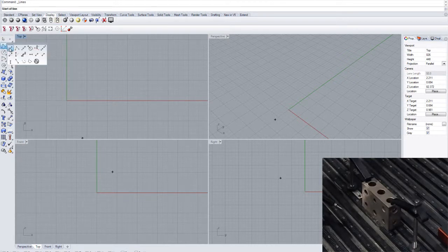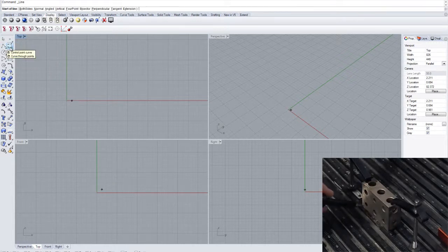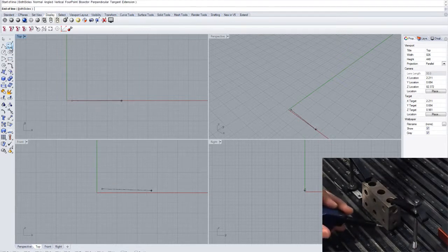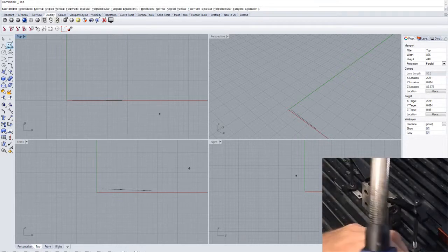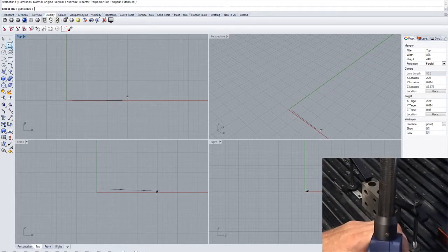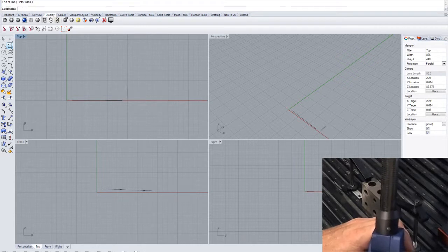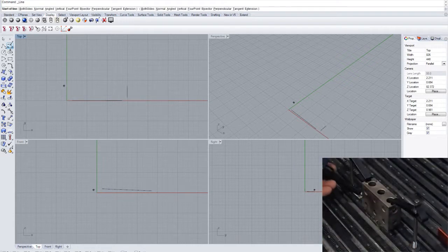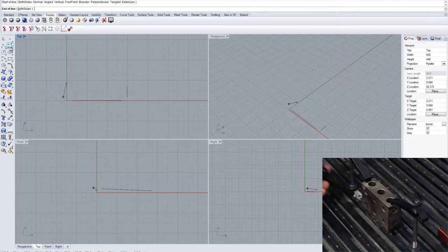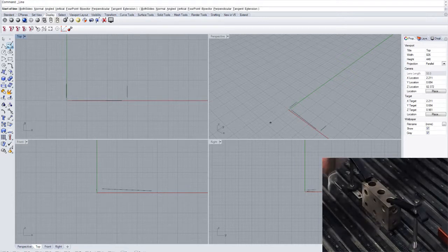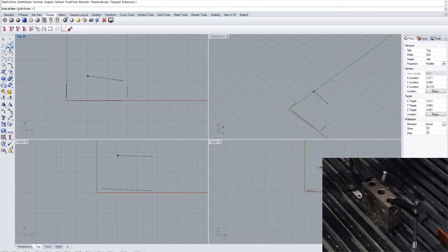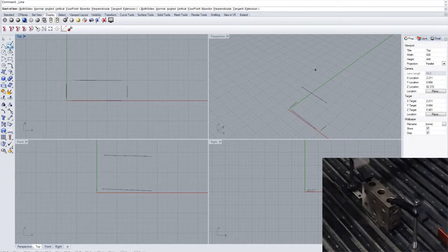Going to hold down our right mouse button so it'll give us a larger palette, and we're going to pick the single line command. So we'll come in here to the part. Let's just pick a single line. We'll use the back button to back up one line on the command bar, and then we'll pick up the function again. And then a third time. And then a fourth time. So now we have our 4 lines to constitute our 1, 2, 3 block.